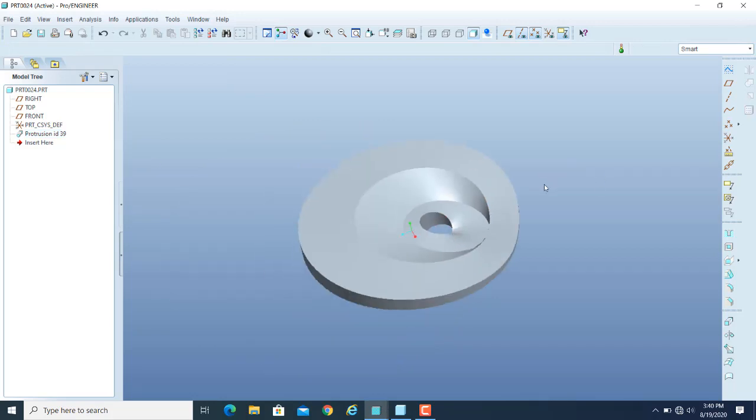So now you can see that parallel blend is basically alternative of the extrude command, and rotational blend is alternative of the revolve command. In extrude or revolve, you can generate the entity, it will be generated, but the cross-sectional area throughout the generated path, it remains the same. Extrusion में या revolve में, you can revolve an object, but throughout the revolution the cross-sectional area remains the same.